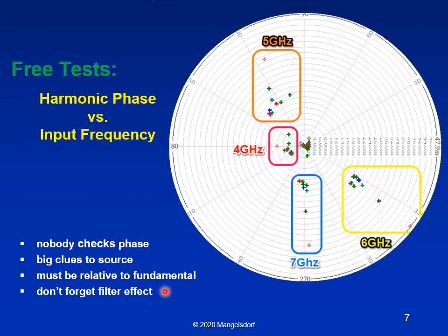That is, further down the signal chain, after this distortion is created, these harmonics are necessarily limited by the bandwidth or roll-off that you have in the signal chain after that point. So what you're looking at in terms of amplitude and phase could be related to the mechanism, but you have to also be sure that it's not related to just the signal path that follows the distortion source.